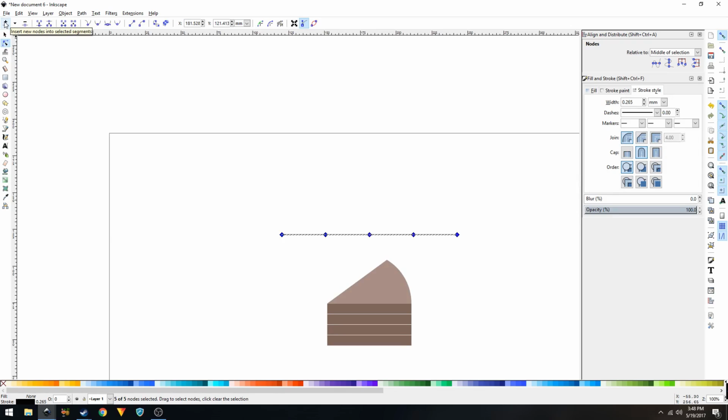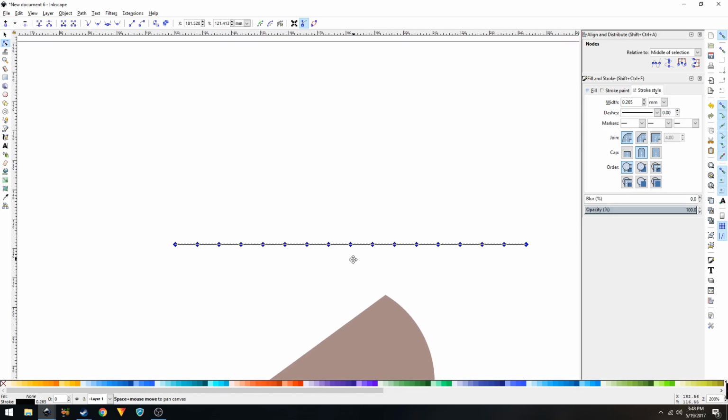Again, click on this icon, and click on it again, and once again, and maybe once again. So you'll have to create these nodes, and then select the first node. And now you have to select the nodes in an odd manner, so I'll just select the first, the third, and the fifth. Go with the 7th, 9th, 11th, 13th, 15th, and the 17th.